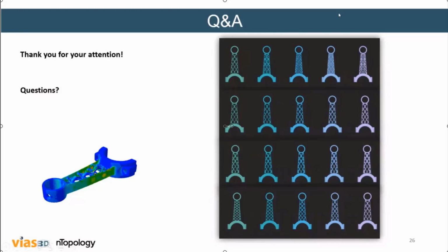And the answer is you can use either the ones on your machine or on the cloud. The next question is, when you're running design experiments, are you actually creating the models? And the answer is yes, they get created and run in the runtime folders, and then they get deleted. You can, however, choose not to delete them and build them up.